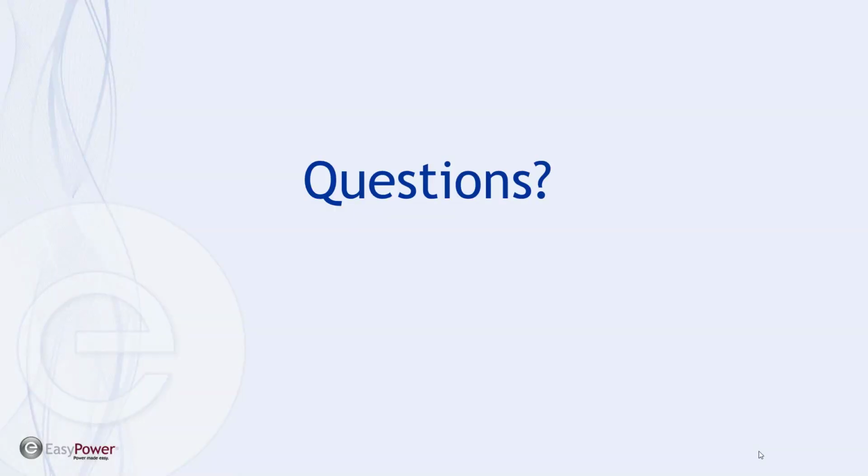Harold's saying he's run into VFD drives where more than one motor was driven by one VFD. How do we handle that? That's a specific case. Rather than take a guess at it, I would refer you to tech support. My first run would be to integrate the total motor, because that's what would be seen upstream.